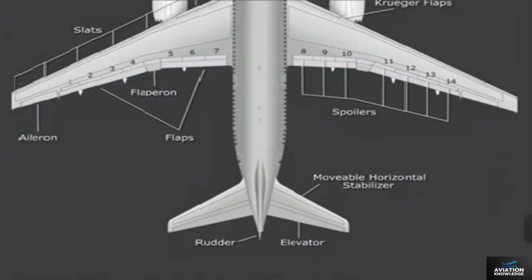The ailerons are located outboard of the outboard flaps on each wing. The ailerons and spoilers droop with the trailing edge flaps to improve slow-speed performance. During high-speed flight, the ailerons are locked out since the flaperons and spoilers provide sufficient roll control. During low-speed flight, the ailerons operate to augment roll control. In addition to providing roll control, spoilers are used symmetrically as speed brakes.